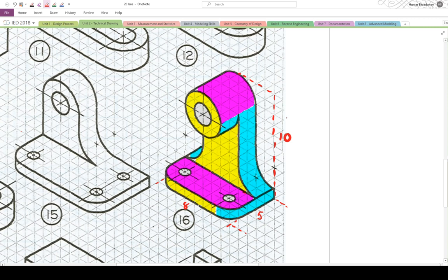I see several different things that we need to do here. We're going to need to put fillets around the edges. There's a couple of holes that are in line with those fillets. There are fillets on the outer edge, and we could make this a circle up here, but if we start with a block, we could just as easily use these as 2 different fillets, and that'll keep us from having to make a sketch to get that to happen. We're going to have to extrude a circle out from this, I don't know what to call that, this expander that comes out, and we're going to have to drill a hole in the whole thing when we're done. Kind of looks like a toilet paper roll dispenser, or half of it anyway.